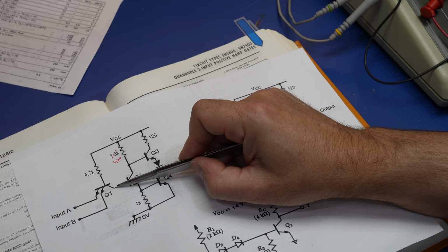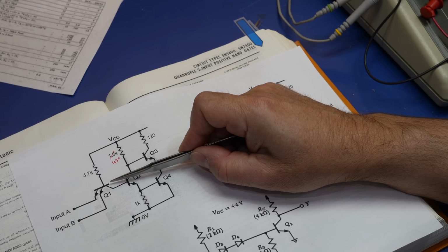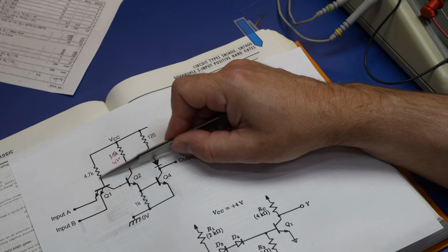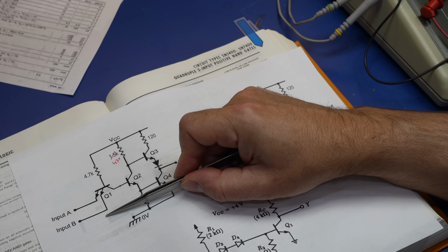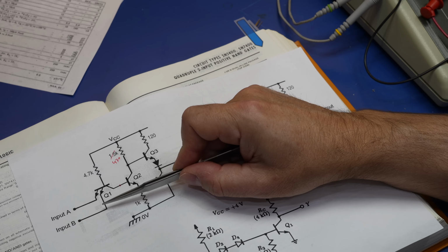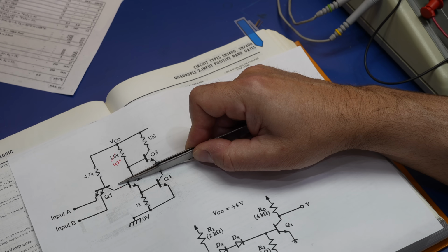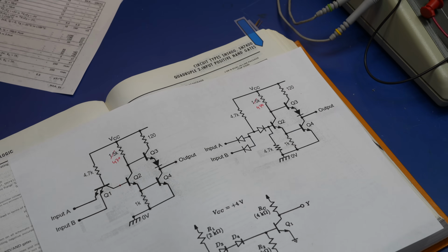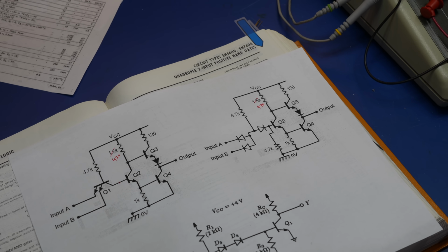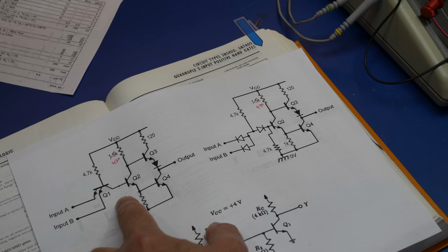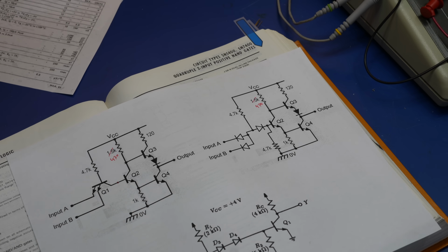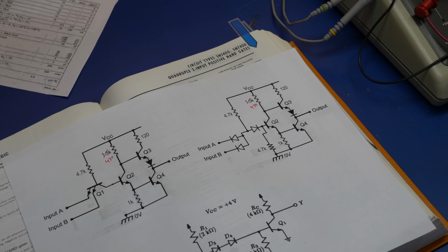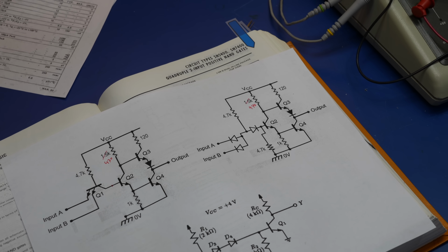It's really a very unusual use of a transistor. It's first used as a diode, then as a transistor, then it gets into saturation, but it's not a problem because when you switch from the transistor mode to the diode mode, it doesn't matter that it's saturated. So it's somewhat genius and somewhat unobvious, so much so that it's not described in the patent. I'm not sure the guy that wrote the patent at TRW understood exactly what was happening. That's why it's usually not explained correctly, because it's very unobvious.